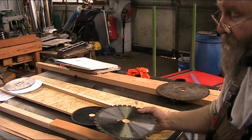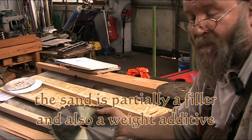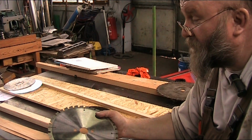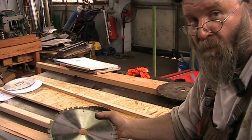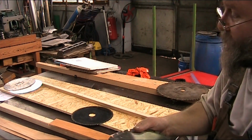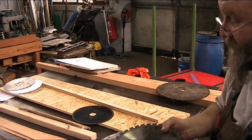Particle board is one of those materials that has a lot of sand in it, and when the blade encounters that sand, it has a tendency to dull fairly rapidly. And so when you're cutting that particle board with your regular softwood saw, that's why it's getting dull so fast, because of that sand in there.